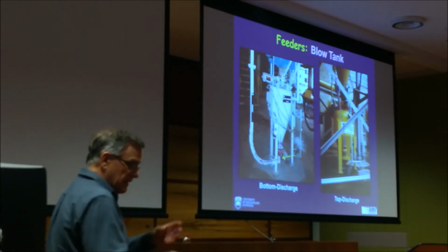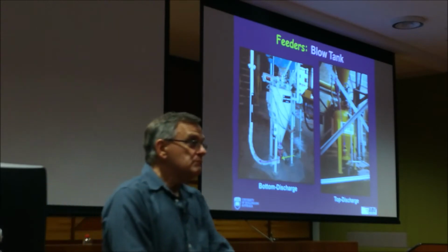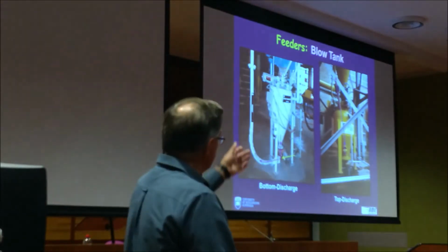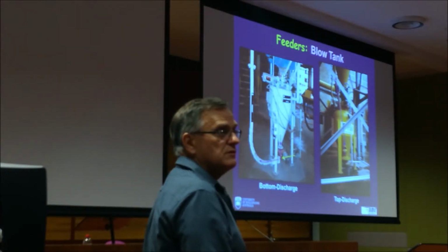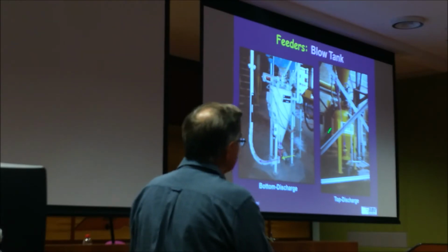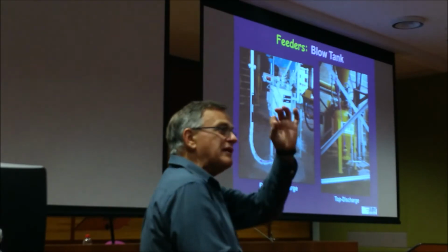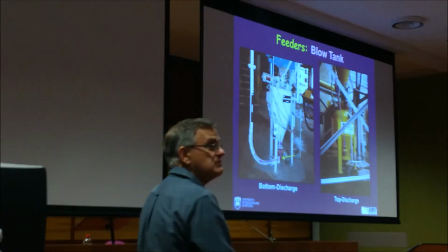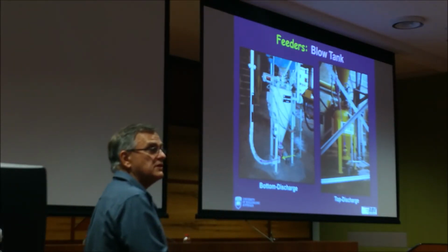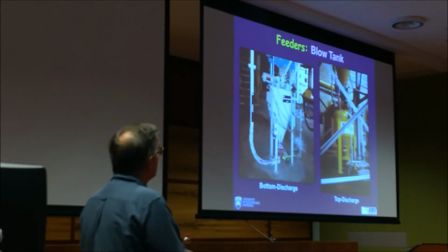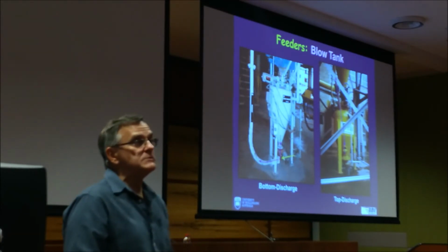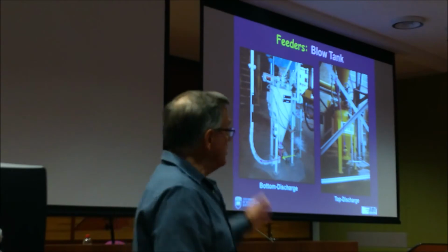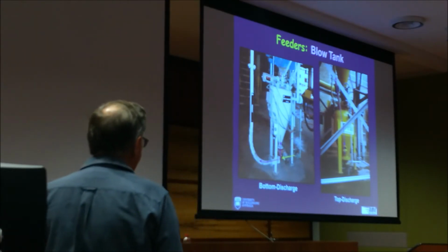So if your blow tank is down in a pit, and you want to bring your pipeline out, it makes sense to use the top discharge. But I would only use top discharge for powders. If you've got any granular material in there, coarse rocks, I will use a bottom discharge. So it is product dependent also, whether you use bottom or top discharge. So that's just to show you different configurations.